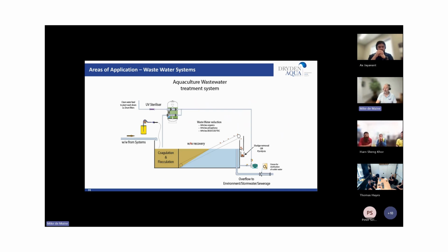This is the wastewater system I was talking about. In this wastewater system, we actually recycle the water through the AFM and UV sterilization to use it for all cleaning processes. So the wash down of the drum filters, the wash down of your floor areas, all of that you can reuse some of your wastewater from that, and the excess can go out either, as I said, biological treatment through pond systems, or you can sterilize it using ozone on the outlet system going out.